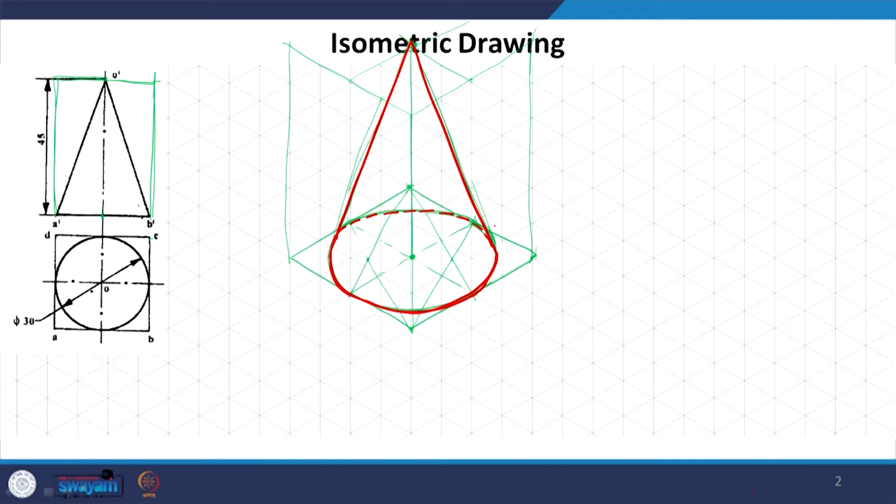This is very simply this cone which is kept perpendicular to HP, and if you agree, this is much simpler to draw than a cylinder, because there we had to draw two bases. One circle in the bottom, the other one in the top, and then we would just join. Here all we have to do is identify where this apex is going to be and draw the base circle, and our job is done. So, this is a very simple position in which we have drawn the cone.